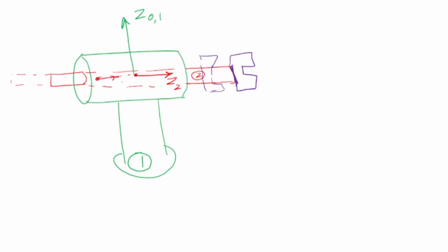And what about the x-axis? So my x-axis is here. So x0, x1 and x2, and x3 is here. So when the Z link is moving on the left or the right, what is happening? It is carrying with it the origin and the frame 2. So x2 can come this side because z2 can be here. When the link is moving to the left, the second frame is also moving with the link, going this left side, like the way I have drawn it. So now there is a distance between here and here. Let me say there is a distance of L2.